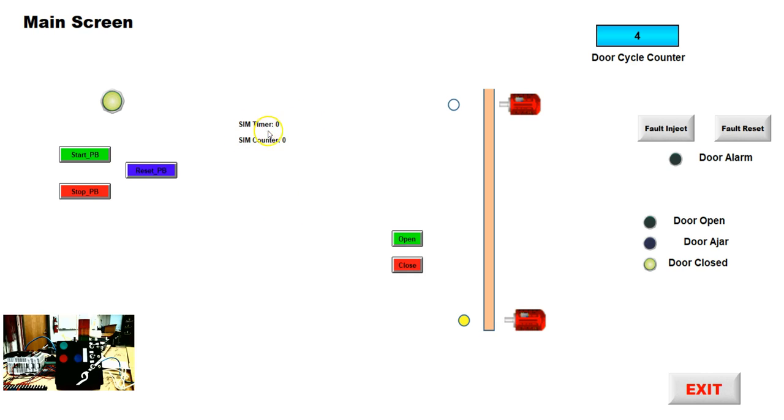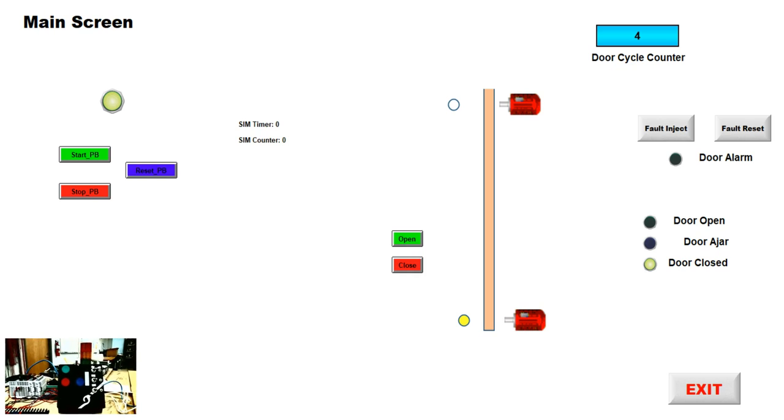These things are invaluable when you're trying to see what's going on behind the scenes, because we have no visibility to the PLC code. But you can put any signal in here and it'll give you visibility. So next time out, we'll do a couple things with this to check out the fault injection. Hopefully this will be okay. Then we'll try to pretty up the screen just a little bit.